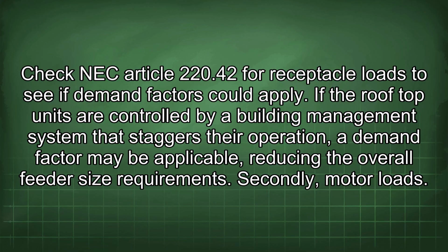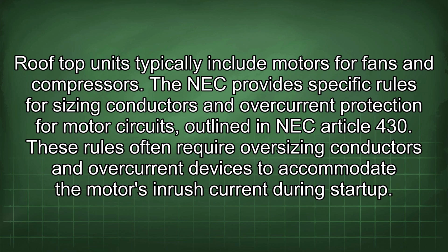Secondly, motor loads. Rooftop units typically include motors for fans and compressors. The NEC provides specific rules for sizing conductors and overcurrent protection for motor circuits, outlined in NEC Article 430. These rules often require oversizing conductors and overcurrent devices to accommodate the motors and rush current during startup.